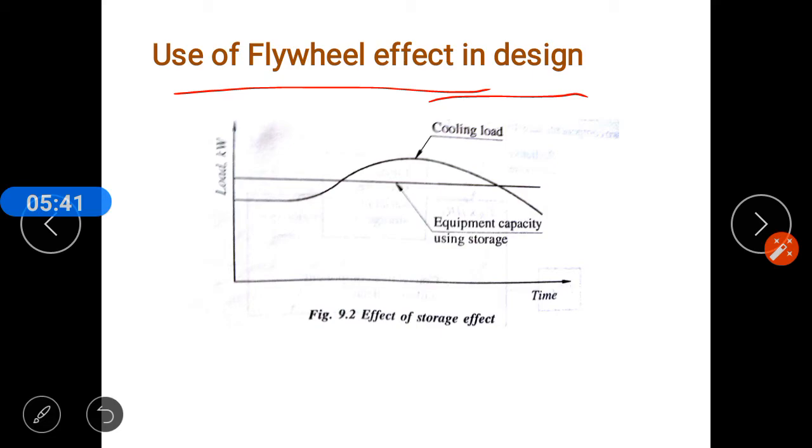In order to remove the pull down load, the air conditioning system is started earlier, around 1 to 2 hours. So the full capacity of the equipment will be used to remove the pull down load, since at that time other loads are not present. Also, the temperature of walls and roof will reduce further, and they are capable of absorbing more heat when load increases again.